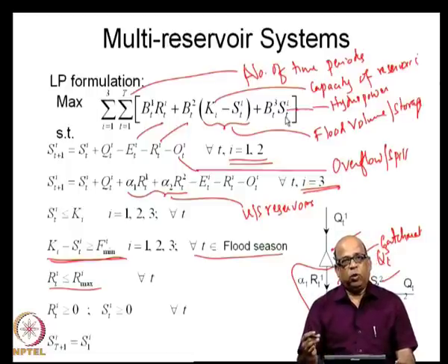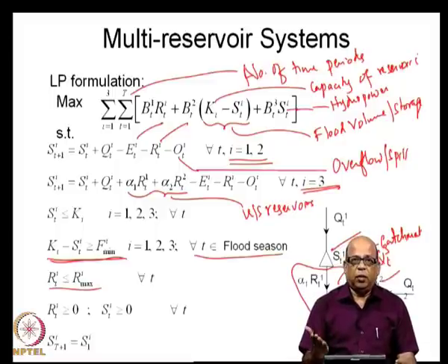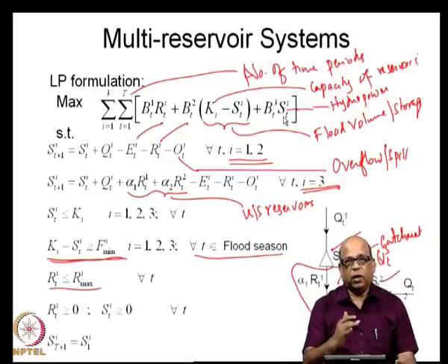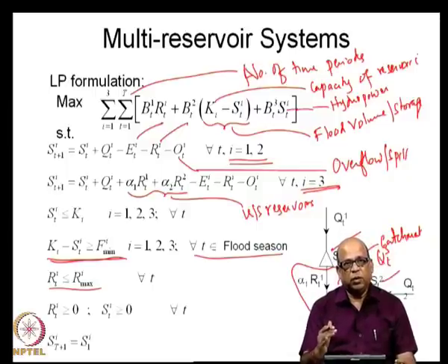But you can also add to the hydropower the discharge that is going through the penstock, and develop the hydropower returns in terms of the discharge as well as the storage that defines the head. And to relate the storage with the head, you can also use the area capacity elevation relationships as we have discussed earlier, and then include those details here.